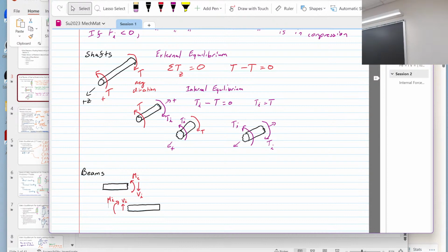Yes, Mark, what's up? This is the reaction force from the wall acting on the bar, to the left. It doesn't mean the force of the bar on the wall is to the left. So that's the reactive force on the bar, which is inside. Look through the force point, that's where there has to be a reaction force from the wall pulling in this direction. We'll go through some of this tomorrow.